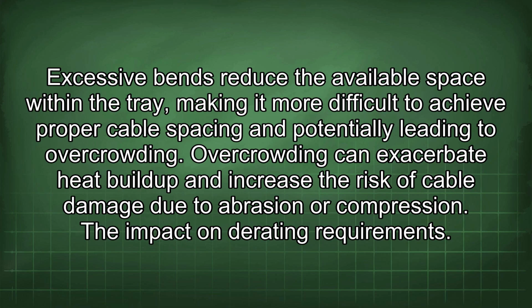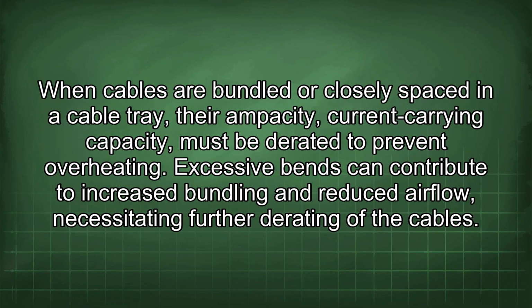The impact on derating requirements. When cables are bundled or closely spaced in a cable tray, their ampacity, or current carrying capacity, must be derated to prevent overheating. Excessive bends can contribute to increased bundling and reduced airflow, necessitating further derating of the cables.